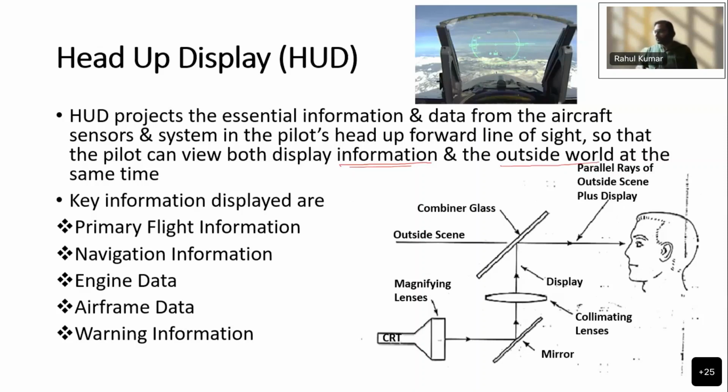Now, this head-up display, as you can see in this diagram, every head-up display contains a display generator, which can be either CRT or LED or LCD, and a combiner. The display generator, as I mentioned, can be either CRT or LCD.